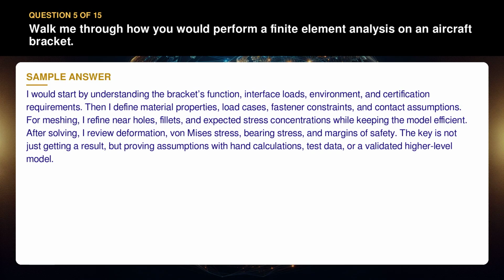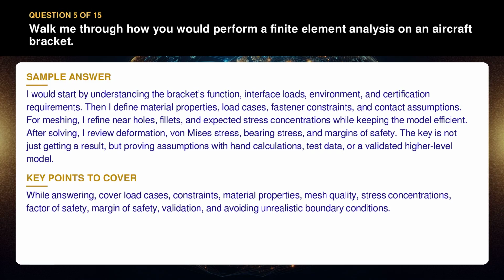The key is not just getting a result, but proving assumptions with hand calculations, test data, or a validated higher-level model. While answering, cover load cases, constraints, material properties, mesh quality, stress concentrations, factor of safety, margin of safety, validation, and avoiding unrealistic boundary conditions.